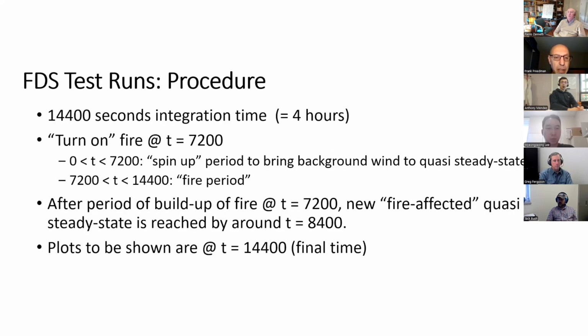There is a spin up time that's required in CFD to get the flow field in equilibrium. So the fire gets turned on. The total simulation time is 4 hours, and I'm turning on the fire halfway into that simulation time. So when you look at the animations, it's going to do nothing for a while, and then the fire will start.